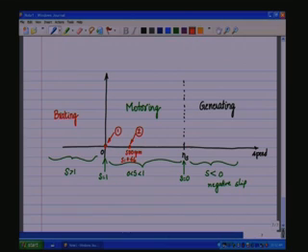And then we had the point which was braking, a slip of greater than 1, let us say somewhere here, where you had rotating with minus 500 RPM. If positive is counterclockwise, then the negative is clockwise direction of rotation, and here the slip S was equal to 1.33, braking.